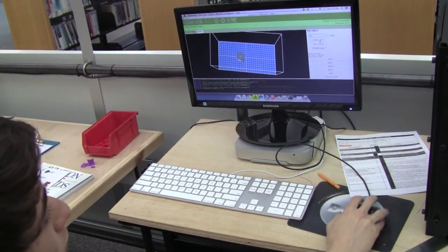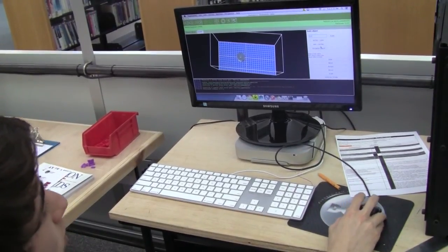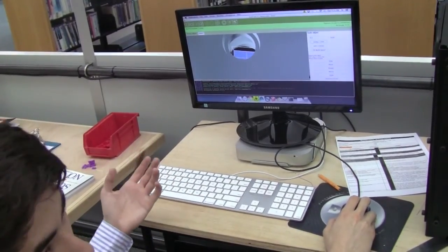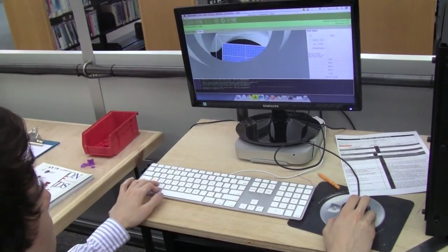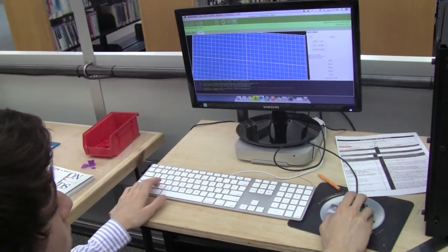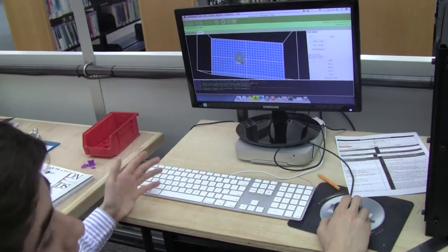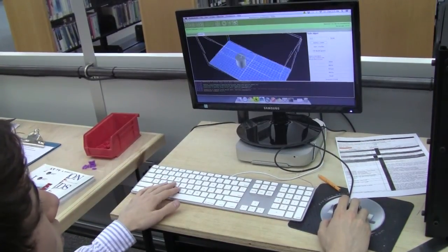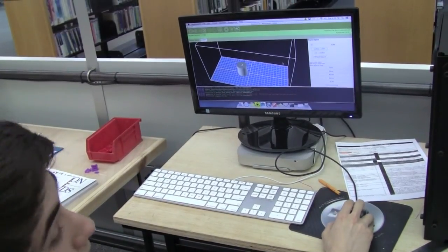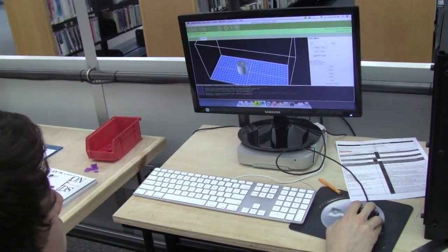So now when you open the model, you have this 5 millimeter object when it should have been 5 inches. And then these buttons will correct the scaling. Let's say this got scaled down to millimeters when it should be inches. This will fix it. Obviously if it's in the right dimension, then it blows it up to huge proportions. But normally if that problem were to happen, it would come in practically microscopic. So then that would fix it and put it back to normal. So that's what those buttons do. If you're planning on modeling in SketchUp, that'll be very useful to remember because I've actually run into that problem a few times. So it's nice to know.